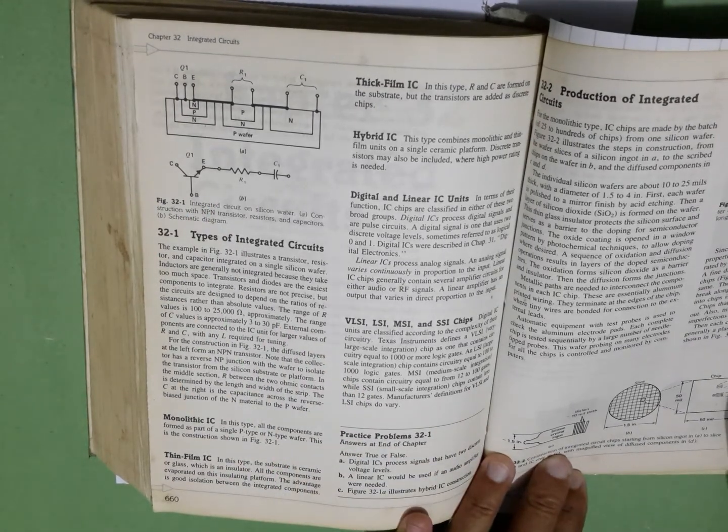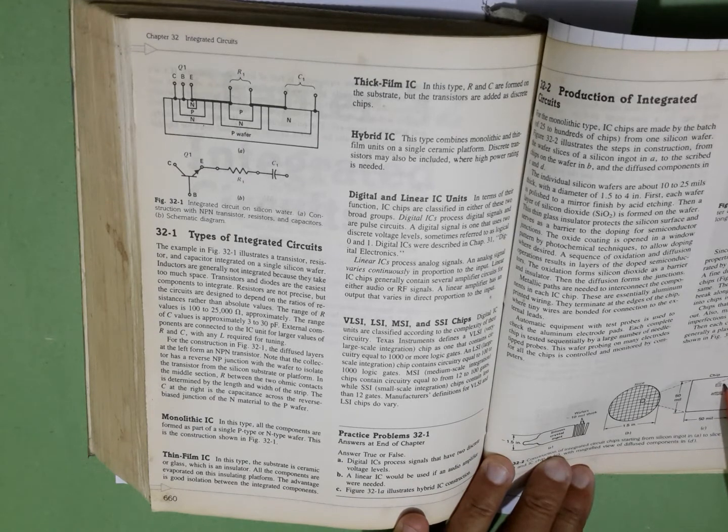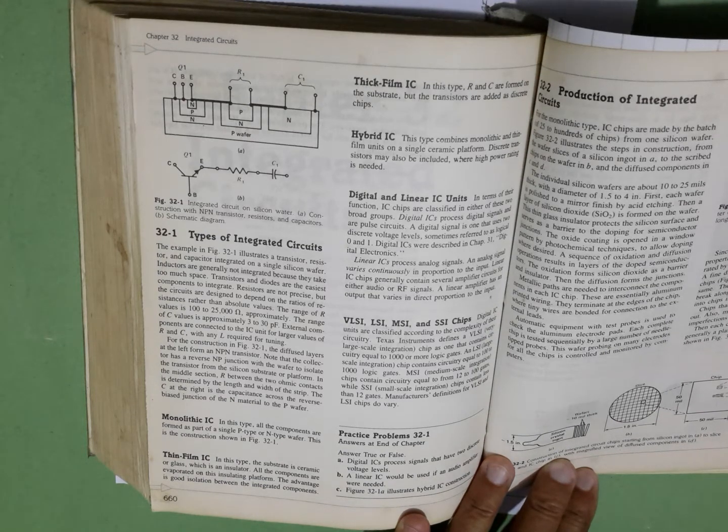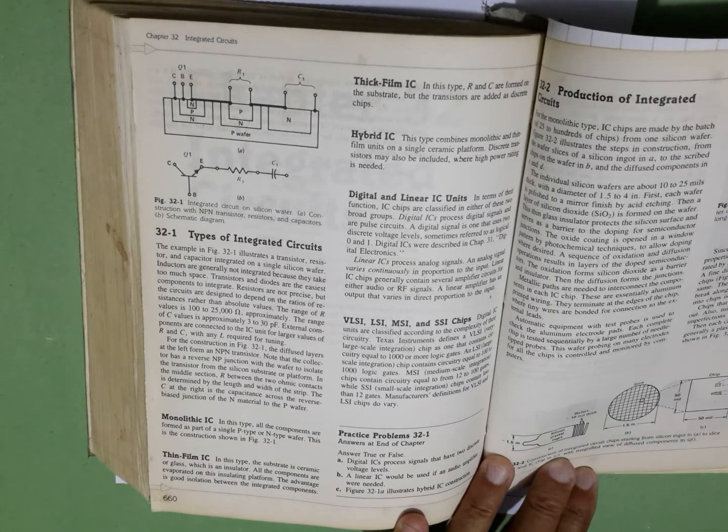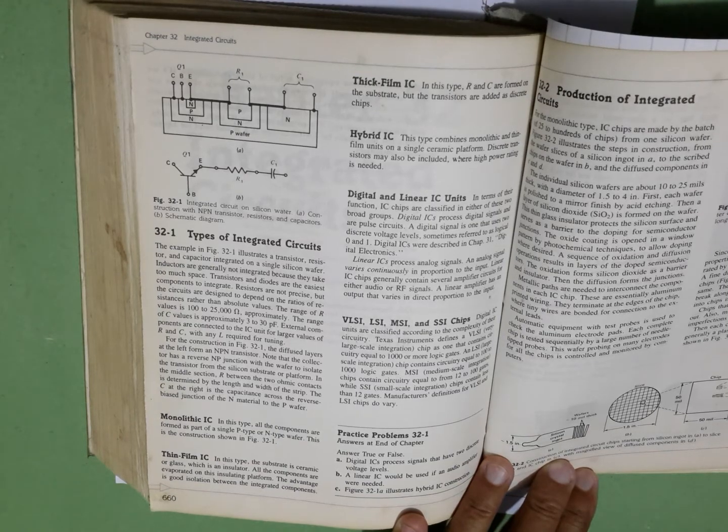This is very small, and the transistor occupies a space of 6.5 mil wide and 4 mil high, with small doping. Then a resistor is formed here on this chip, and it is 12 mil long and 2 mil high. This is a dual inline package. This is a round top, this is a flat package.